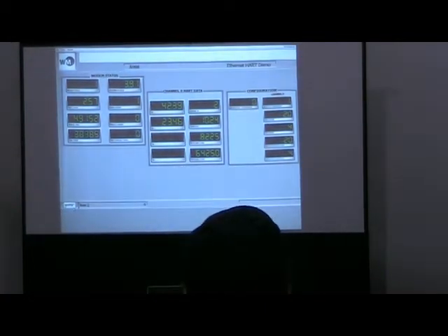You were saying something else, Chuck, related to an alarm? The 1024 is the bit that shows there's a problem with that particular channel. It's out of range or something to that effect. We didn't break it down to show individual bits. Individual bits would tell you exactly what's wrong, and we threw this together in a short fashion to say something's wrong. It could be out of range because it's set for 50 degrees Fahrenheit, which is the 0 transmitter, manufactured calibrated to 4 milliamps, and we're much below that with the ice pack on there.